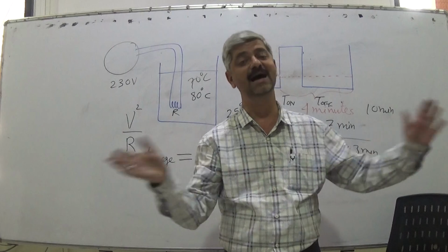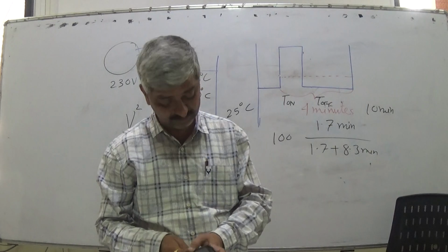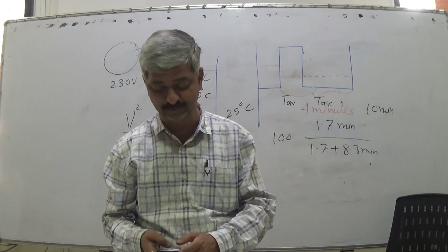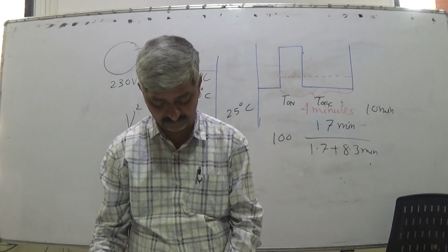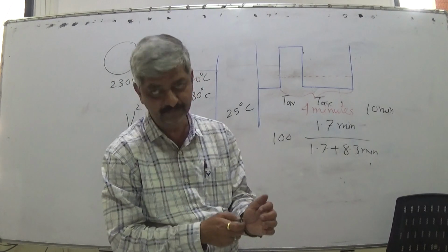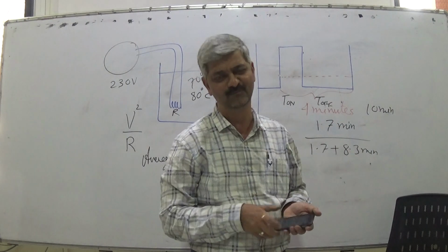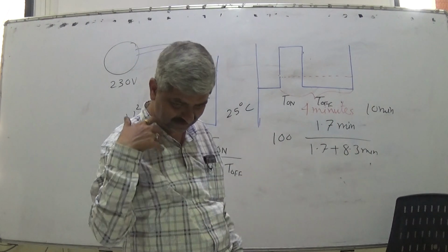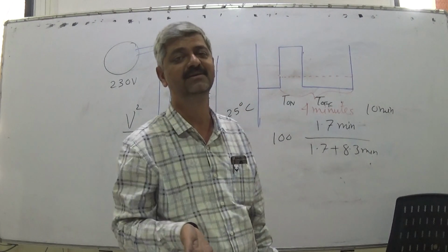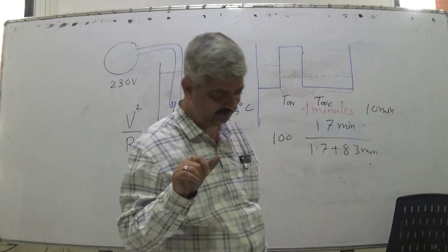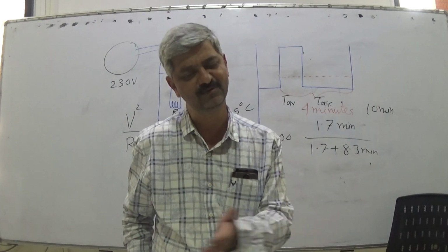But if the window is too large, it will not be of use. Considering the speed of the process, temperature is a very sluggish process. So 1 minute or 5 minutes is negligible time, in the sense that it is too short for significant changes to occur. You can make it 10 seconds on, 50 seconds off.